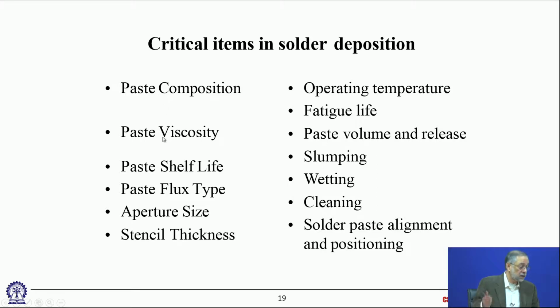That's where the rheology becomes very important. The solder paste rheology has to be right because it has to fill the opening in the stencil properly. It has to form a nice column over there, a nice pad over there, but then it should not lift off when you lift off the stencil. So the solder paste composition, paste viscosity. And what is solder paste? Well, paste is basically little particles of solder, spheres of solder material, and flux, and some binders, complex rosin binders.